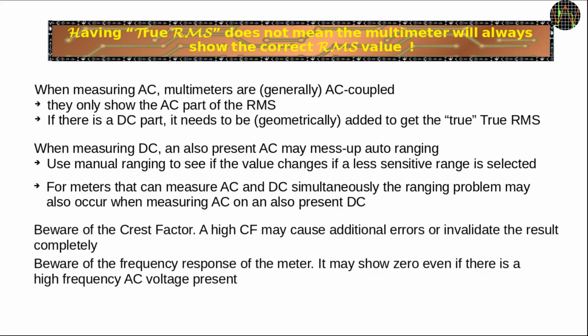Lastly, there's the crest factor out there to get you by degrading accuracy, and of course the bandwidth limit of your meter, reducing or even completely zeroing the readings at higher frequencies. Lots of things to keep in mind when doing such a simple thing as measuring AC.